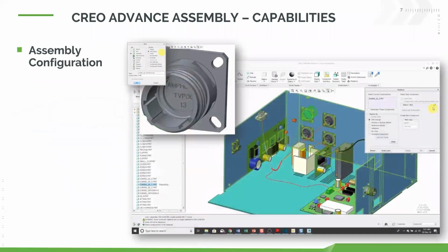Another thing that we oftentimes work with here is assembly configuration. We have tools such as interchange groups for things like fastener attachments, where they're always going to go on the same way. You shouldn't have to spend time setting each one up individually. So if it's something like a custom electronic fitting where you're just trying to make it mount, you're just able to pick the face that goes on and have that all laid out there for you.